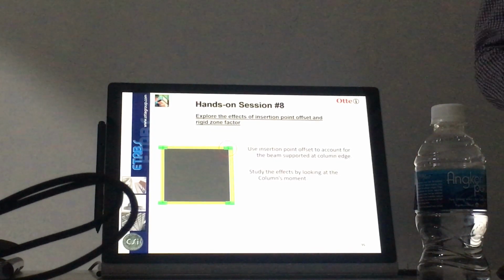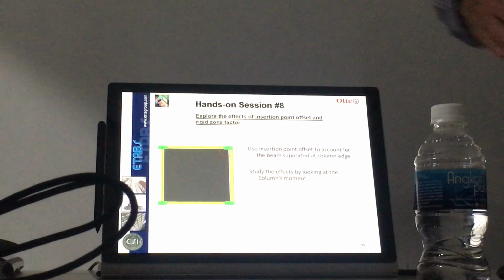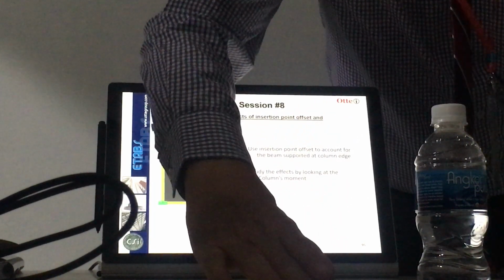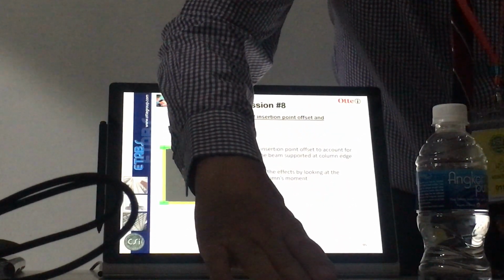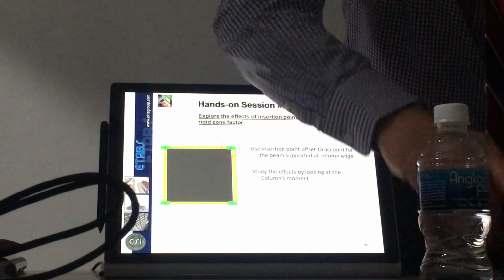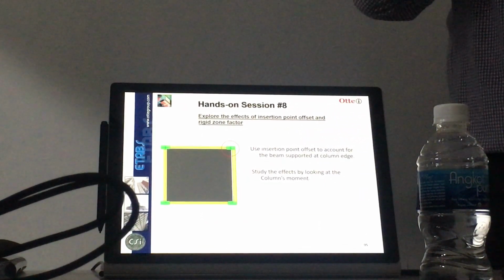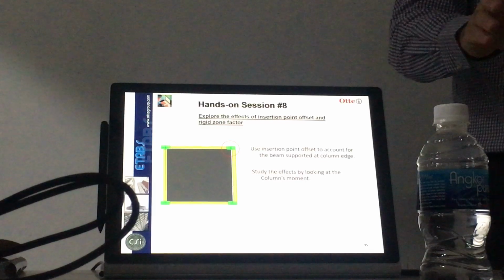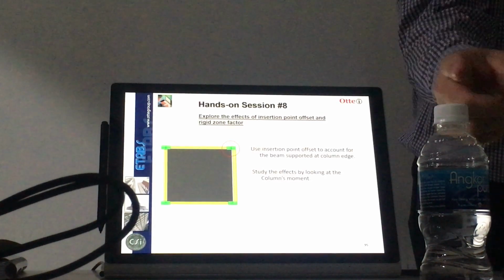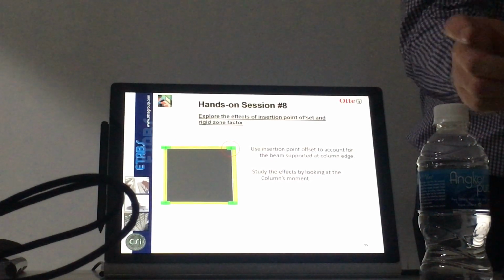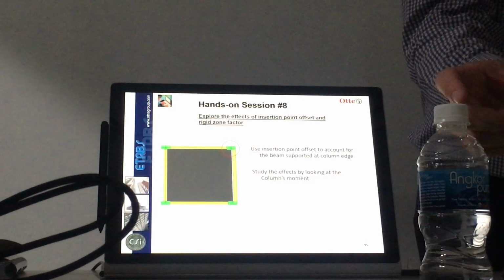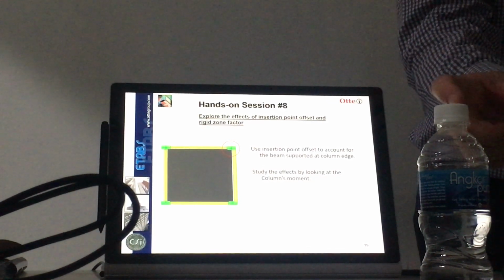It will fall off. It will not be connected. But I know I can put the beam like that. It will not go away, right? Because you have a ridge section here, right? Column is like that, right? Or the beam is actually sitting somewhere here, right? Center here, right? So a more explicit way to account for this is to create a link. A link is a connecting between 2 points, and you can specify the behavior accordingly.